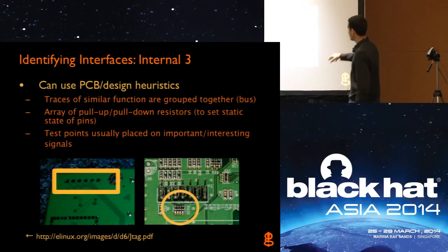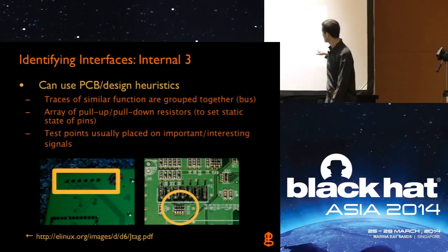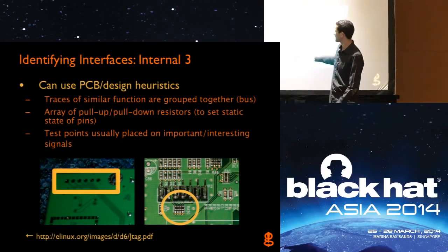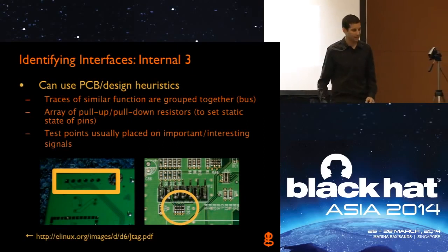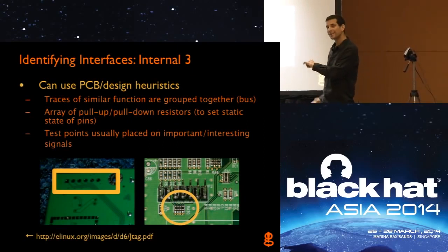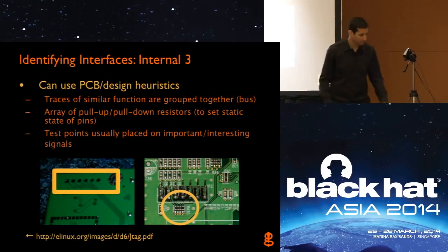So when I saw that, there were a few other connectors on the board, but I saw this one with the resistors right there, and it just seemed very obvious to me, and that ended up being the JTAG interface. I didn't know which pins, but that's where the JTAGulator came in, right? So I could at least identify it and then go to the next step.